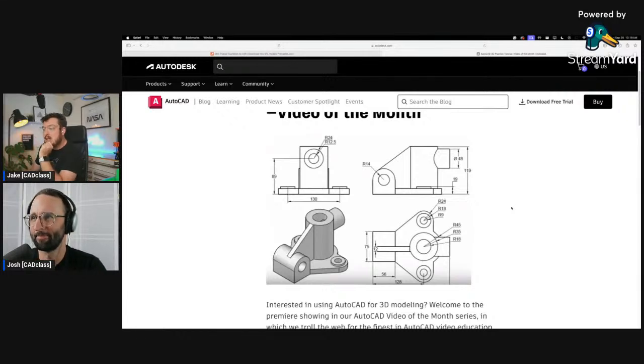As far as the profile goes, it's almost like a sideways heart shape. That seems to be the most complicated, so it makes me think that it wants to be boosted upwards first. This little mound on the left-hand side, I can imagine being a rectangular extrusion, and then a cut from the top, or maybe a fillet, and then a hole. But I'm likely going to make that as a separate operation, just so I can still make it symmetric. I'm also seeing that these 2 circles that are not very tall on either side are vertically constrained to that large circle at the very center.